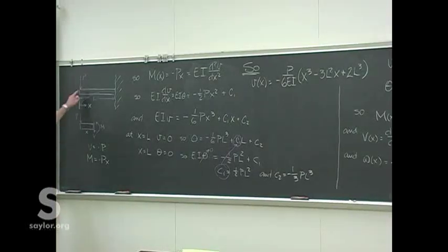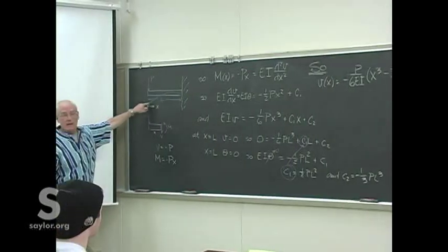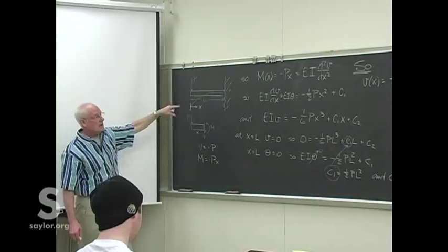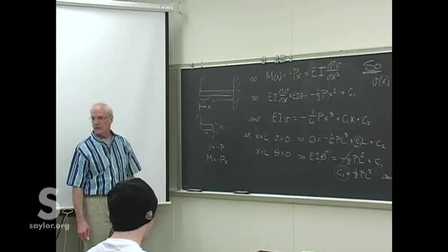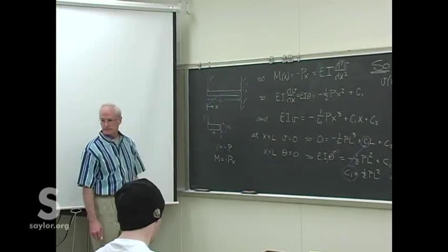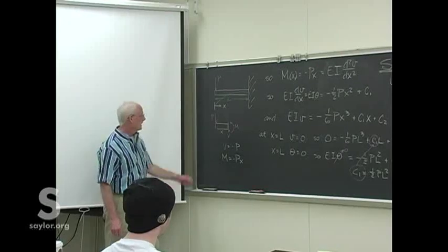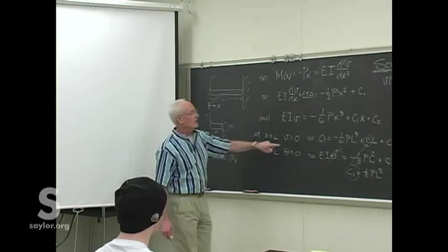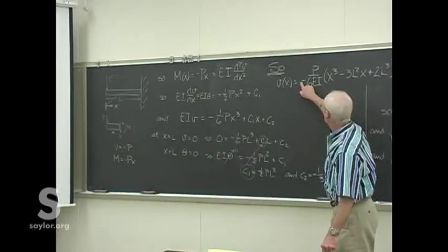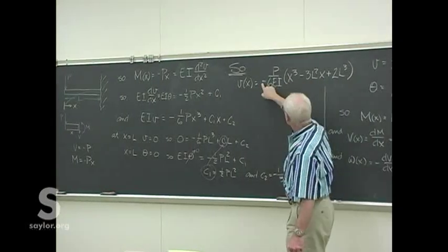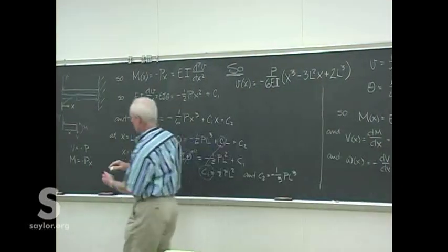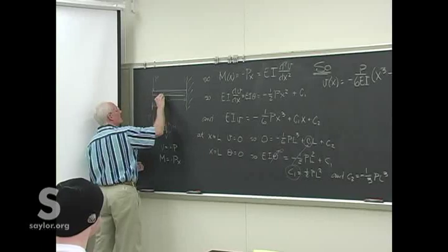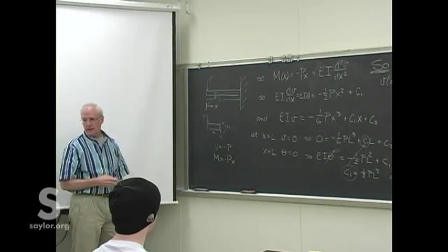So you've got a value for P, a length of the beam L, a material chosen E, and a cross section I. You can predict exactly where the beam's going to deflect under this kind of load. You always start by putting everything in the positive direction. Yeah, because if you do that, then you've got the minus sign that carries through. Because this tells us, when we put in all these values, you'll get a negative number for this, which means that the deflection is that far below the neutral axis at that point. And that works in all cases.